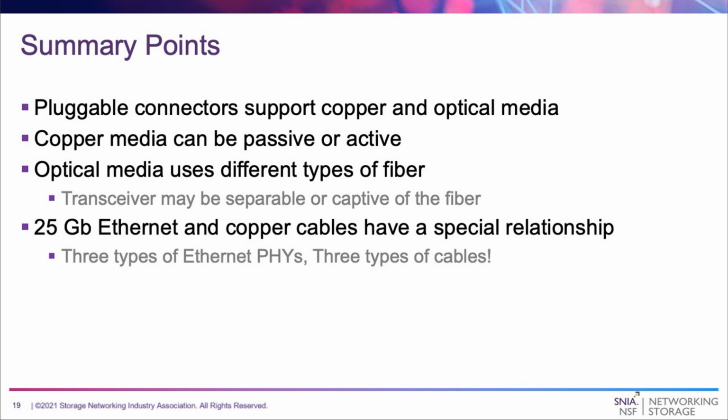So in summary, pluggable connectors support both copper and optical media. The copper media can either be passive or active. The optical media uses different types of fiber, whether it's single mode fiber or multimode fiber. And the transceiver can be separable or captive of the fiber.